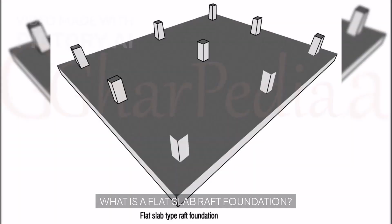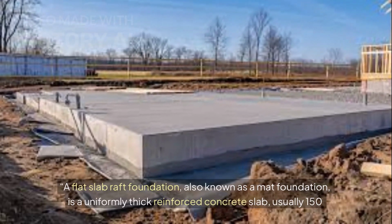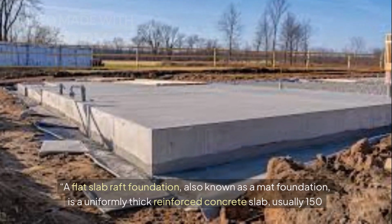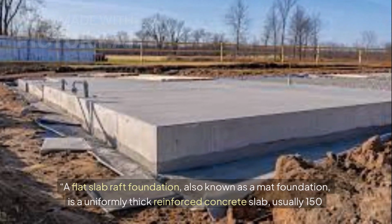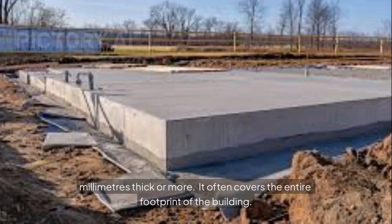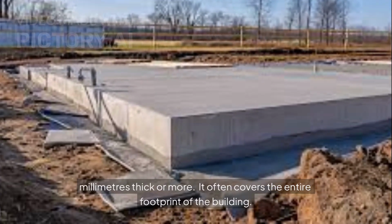What is a flat slab raft foundation? A flat slab raft foundation, also known as a mat foundation, is a uniformly thick reinforced concrete slab, usually 150 mm thick or more. It often covers the entire footprint of the building.